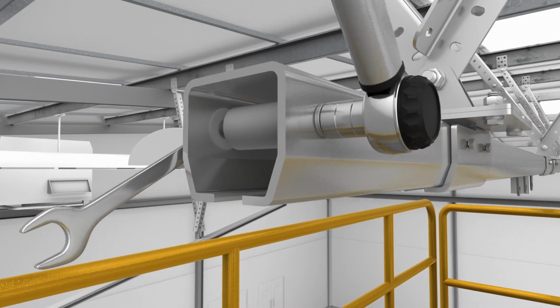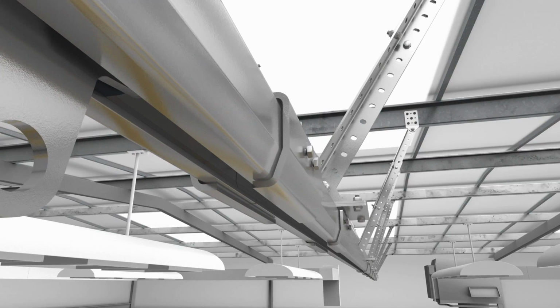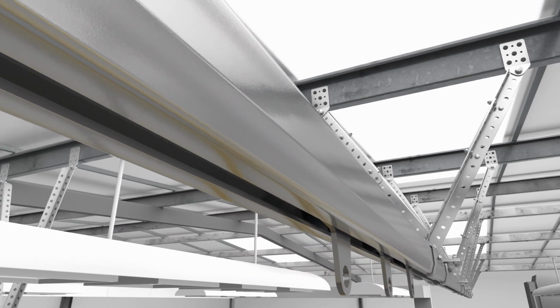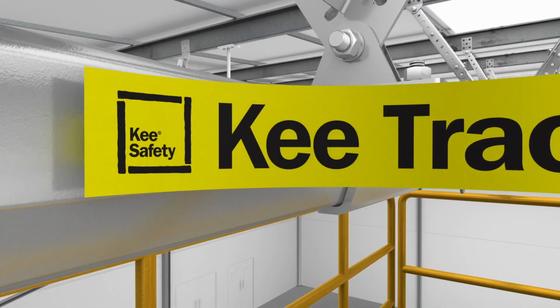Tighten all bolt assemblies to the torque value shown in the torque settings table. Ensuring the rigid rail is free from contaminants, such as dirt and grease, apply the self-adhesive Kee Track branding sticker to the extremity of the rigid rail section.